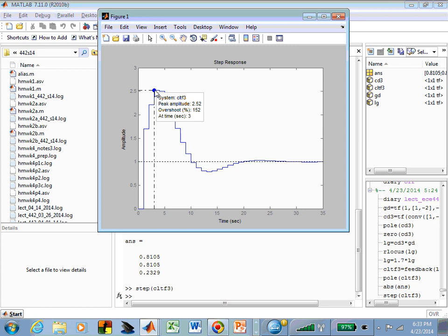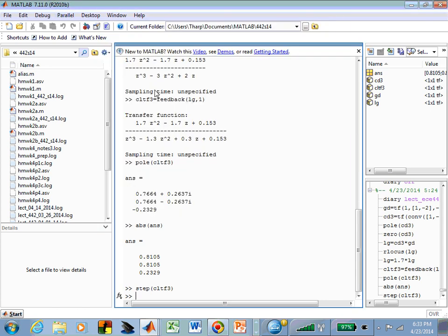So now the question was, I think, in the PI controller, we requested closed loop pole Z deltas at 0.9 plus or minus j0.1. The question I think now is, what if we had instead made our Z delta 0.76, whatever this was, plus and minus j0.26? Is that the question? The answer is I don't know. We would have to try it.